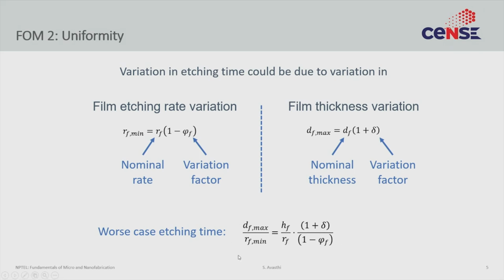The point of this whole argument is to always be sensitive to variations that can occur. So when you are chaining processes together, you must also remember that variations also chain together. When the deposition is the first step, you only have to worry about deposition uniformity, but by the time you come to etching, you have to start worrying about the uniformity of all the processes that preceded the etching in order to really ensure you get a good yield.